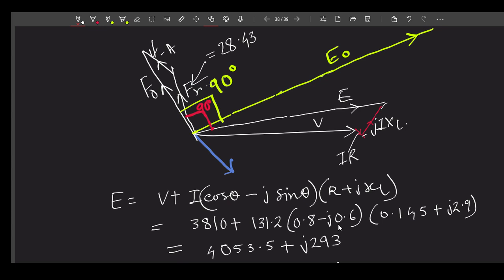Here armature reaction MMF is not getting a constant reluctance path, rather its reluctance is variable in nature, but still that is a good approximation, won't cause much problem.